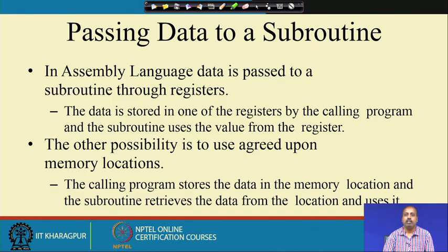So, you can use one register to hold some parameter that you want to pass to the subroutine. But since the number of registers is limited and they are also used for other purposes, it is better that we have some other option, and that option is via the stack. Memory is very large compared to the data space requirement of a program, so we can use the stack for the transfer of these parameters.